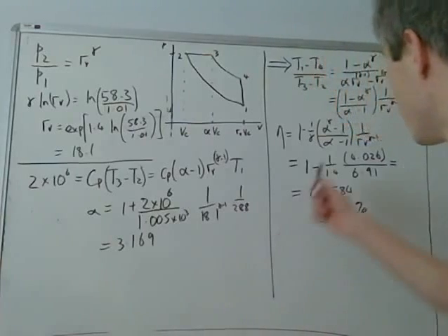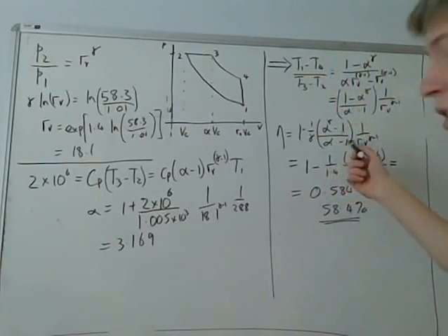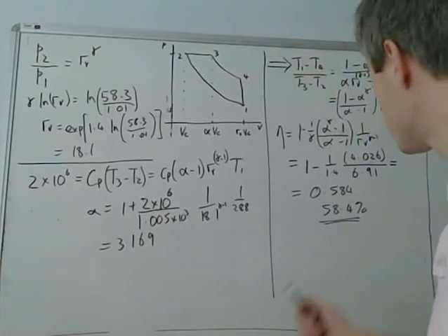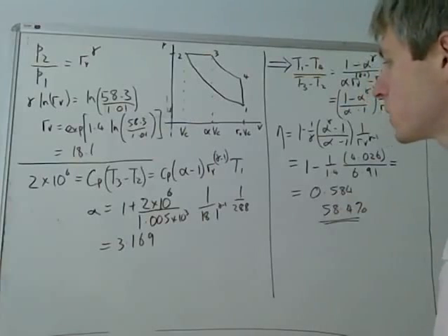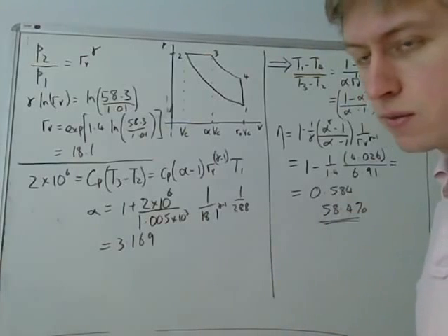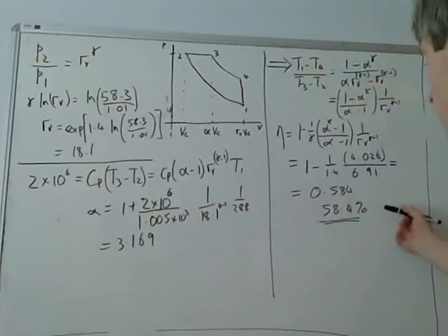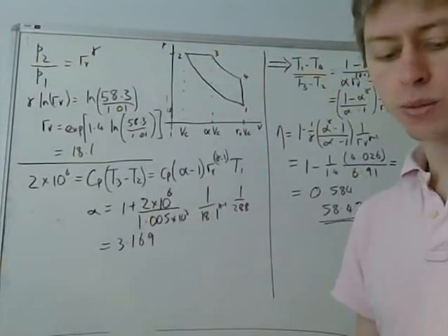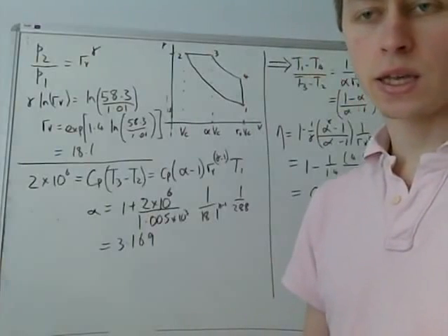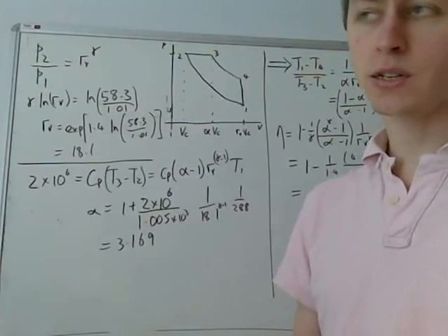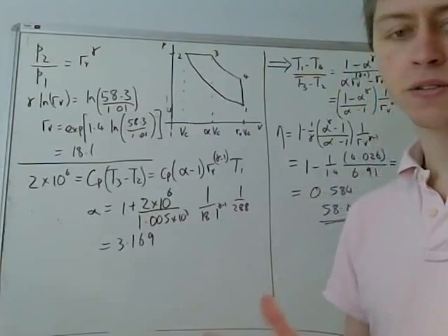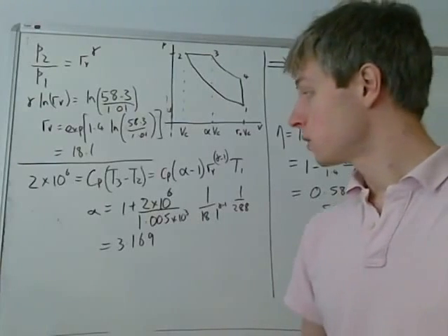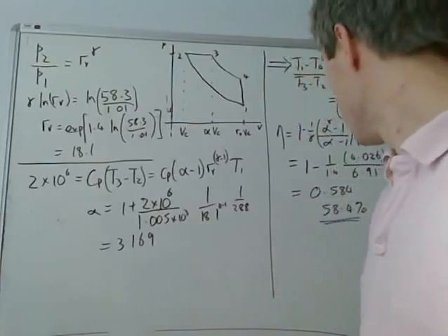So the diesel engine, although it's in principle not such an efficient engine because we're burning at constant pressure, because we're actually running with a significantly higher compression ratio, 18 versus 5, we're achieving a higher overall efficiency. But it really exercises your ability to apply the isentropic compression and expansion calculations, to apply the first law, and to use the ideal gas equation as appropriate.